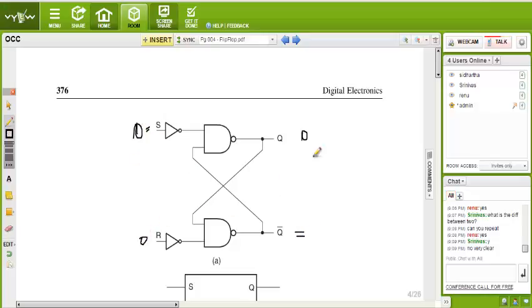And previously suppose it was 0 and it was 1. Check with that. This 0 comes here. And from that 0, here is 1. Now what will be the output of that? 1. Good. This 1 goes here. And this 0 is inverted by the inverter. Then what will be the output there? This is 0. So see, whatever the previously stored output is remains unchanged.